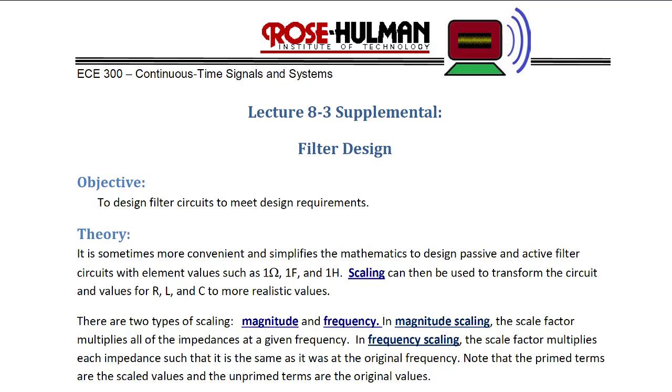It is sometimes more convenient and simplifies the mathematics to design passive and active filter circuits with element values such as 1 ohm, 1 farad, and 1 henry. Scaling can then be used to transform the circuit in values for R, L, and C to more realistic values.